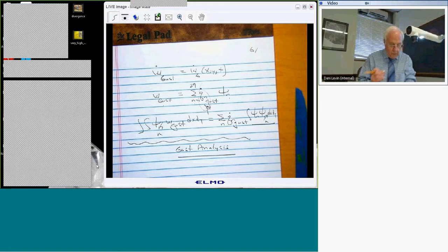If it were a cantilever model, I'll make it easy for myself, you probably use the first bending mode, because that would be the mode most likely to respond to the gust. If you want to do the real airplane, you probably have to use rigid body translation as well as maybe first bending. You might have to use two modes. Yeah, the heave mode plus first bending.